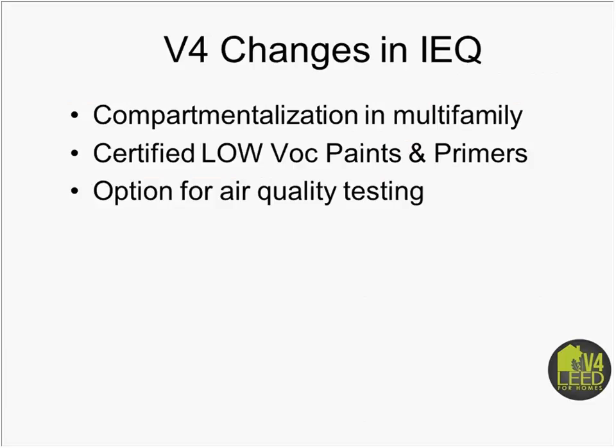So what are the biggest changes in IEQ? Really, the big one is compartmentalization in multifamily housing. Not only are we now looking at air sealing the building shell, but it's really important to start looking at air sealing the individual units from each other.